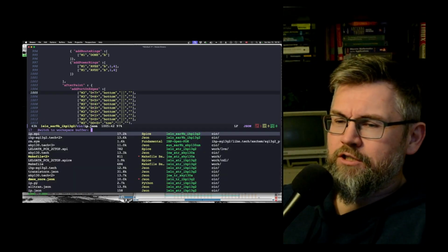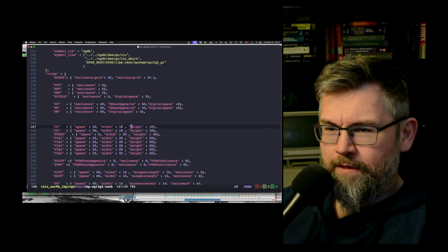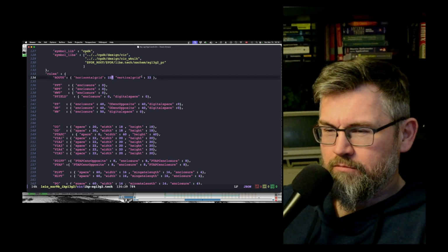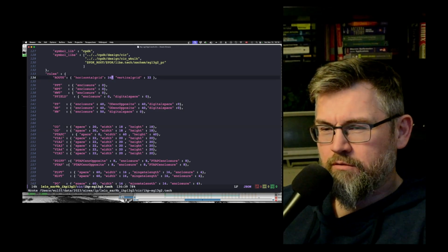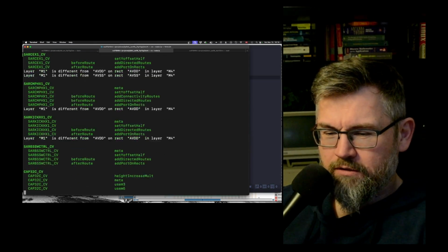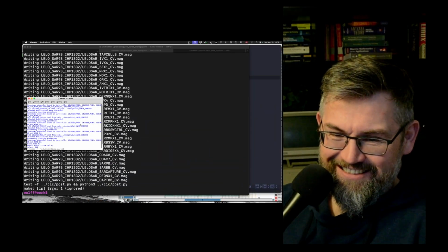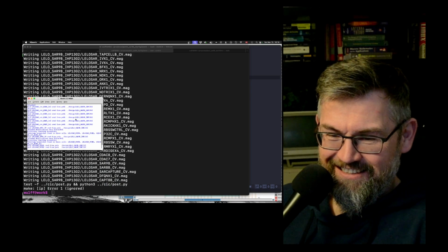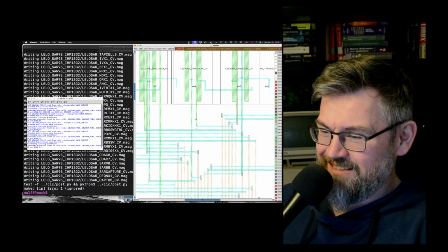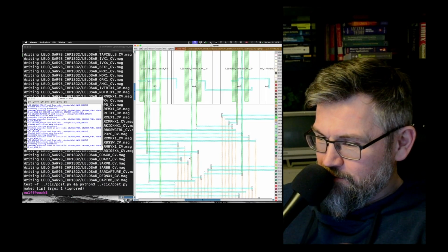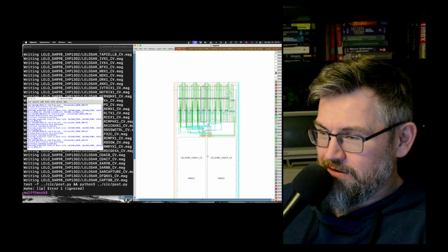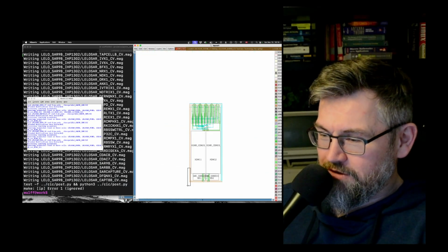Okay, let's cheat a bit. Cheating is good, so if it worked with 100, let's just change that to 22 and see if that fixes the problem. No, that just gave me a bunch more DRC errors.